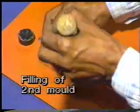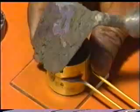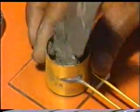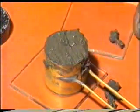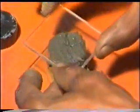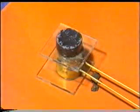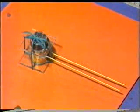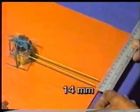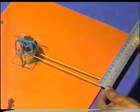The second mold is filled with fresh cement paste. The entire procedure of filling, covering with glass plate, placing the weight and tying with the thread is repeated. The distance between the tips of the indicators is 14 millimeter in the case of the second mold.